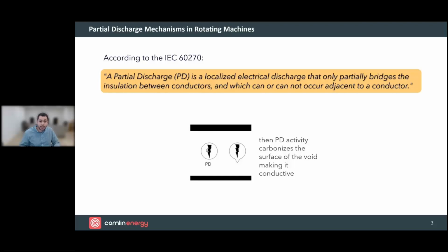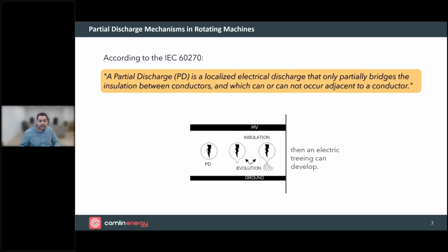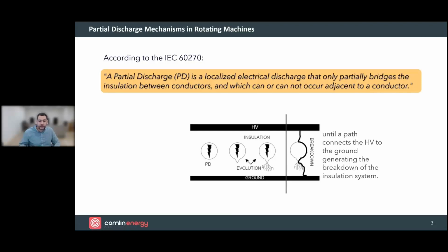Some may be conductive, and these may lead to the spread and the growth of that void, an increasing size of the defect. We can see electrical trees here in the illustration. And once you've had some defect and some carbonization, the materials are now compromised, they're weakened.